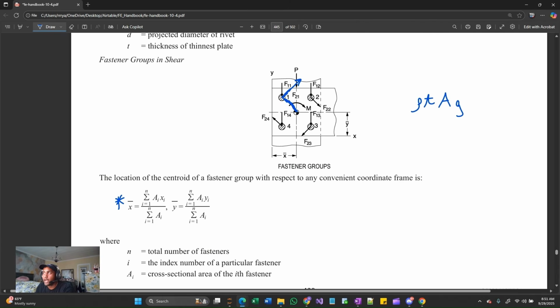That's going to be the weight contribution. Because the thickness, the gravity and the density are all constants throughout this entire equation, we end up removing all of those, and it looks like we're taking moments of areas, but really we're still doing the same thing we have been. We're taking moments of forces, just in a simplified format.